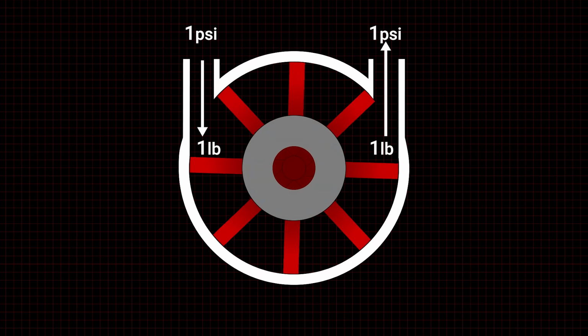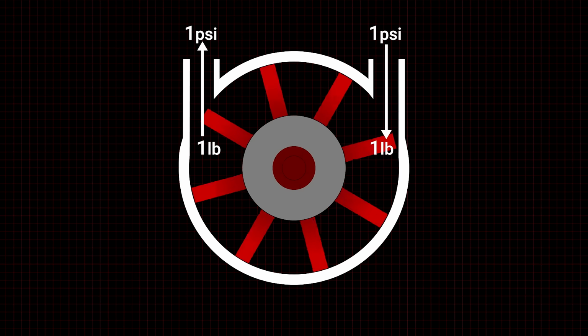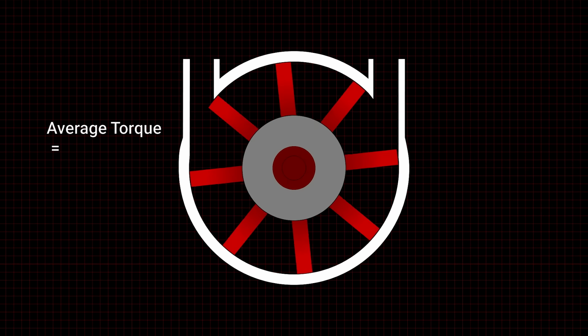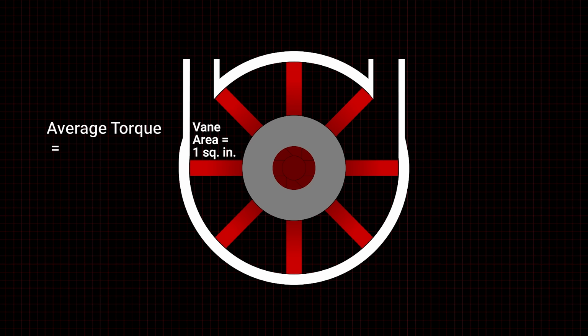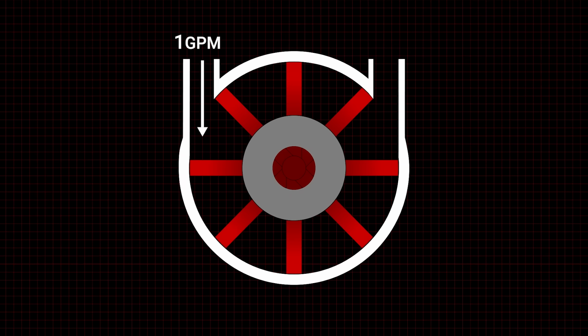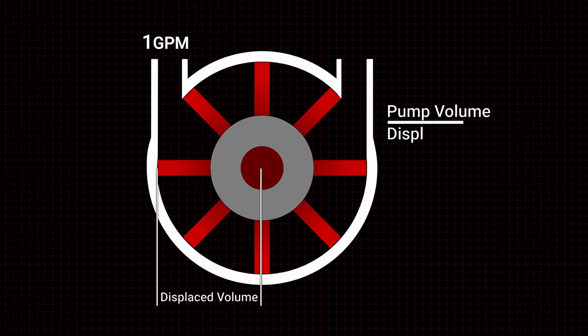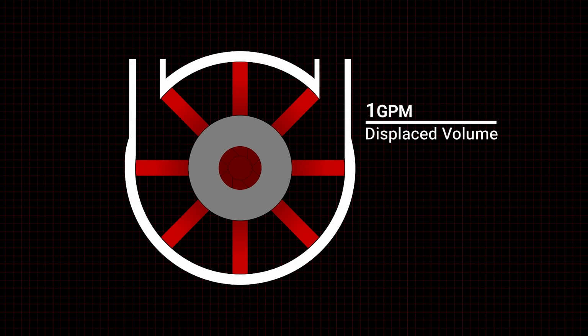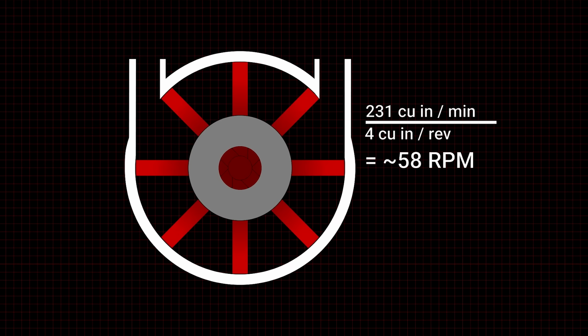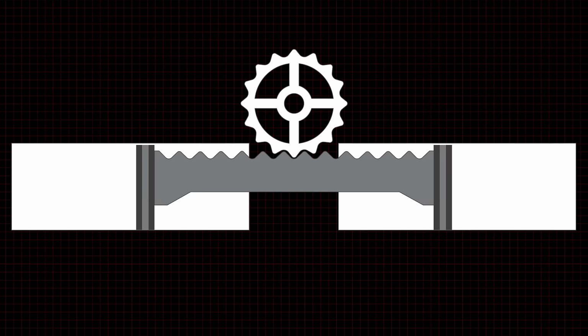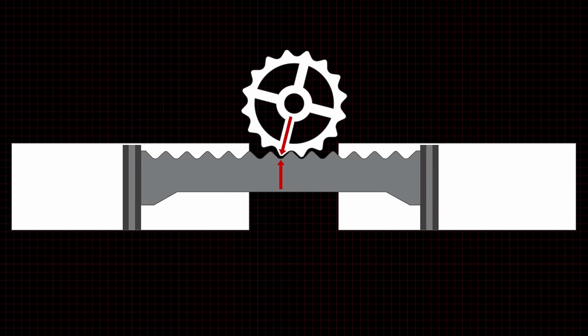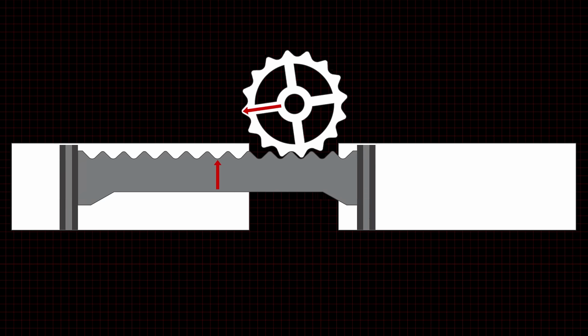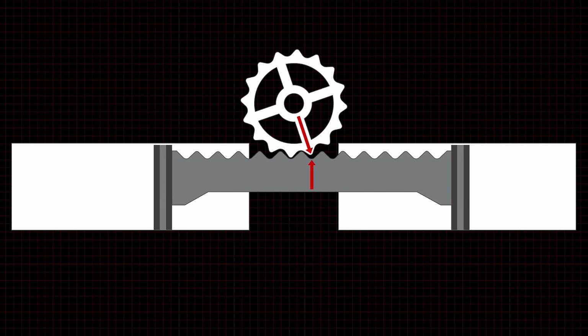Continuous rotary actuators have the same surface area when spinning in either direction. Their power is dictated by the surface area of the vane and the diameter of the vane disc. The speed, or RPM, of a continuous rotary is determined by the pump GPM and the actuator total displaced volume. Divide the pump volume by the actuator to determine the number of revolutions per minute. Some rotary actuators use linear pistons to create limited rotation actuators that are useful for steering or swinging heavy loads.